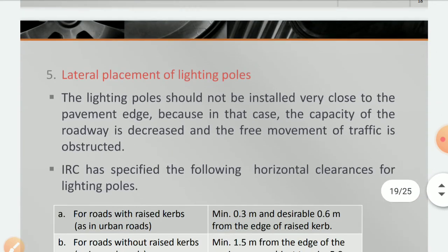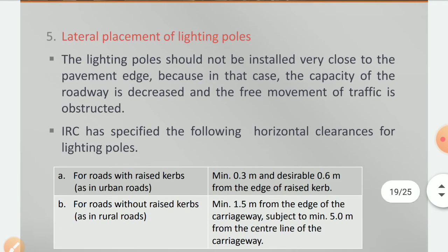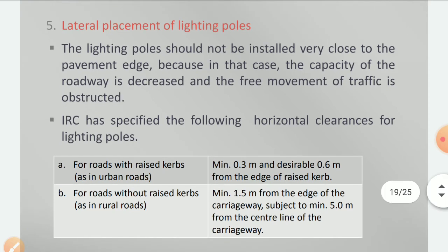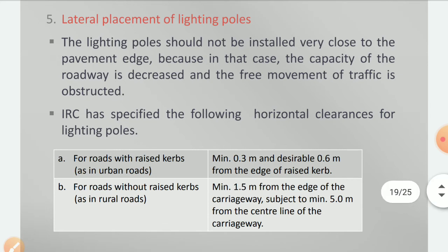considered. Then lateral placement of lighting poles. Once again, what types of luminaires are required and what considerations you have to make while designing a lighting scheme, we have discussed. Now the lateral placement of poles. The poles can be placed in different positions. On highways you might have observed that the poles are in the middle.